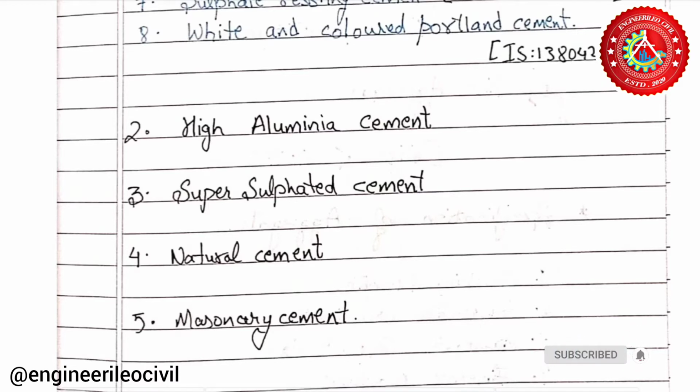Masonry cement is the last type of cement. This is manufactured by grinding Portland cement clinker, limestone, gypsum, and air entraining agent. These are ground finer than high early strength Portland cement. This is used for mortar in brick masonry. Limestone and air entraining agents impart plasticity and workability, and shrinkage is fairly low.